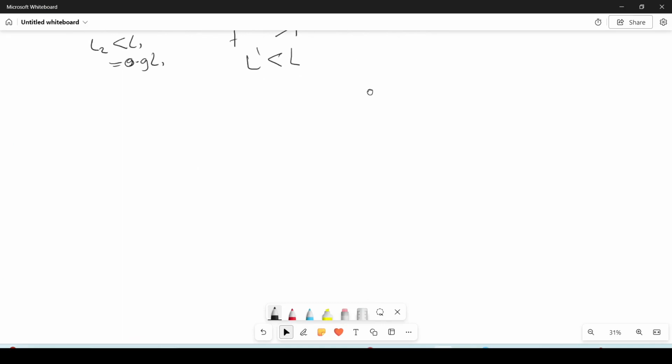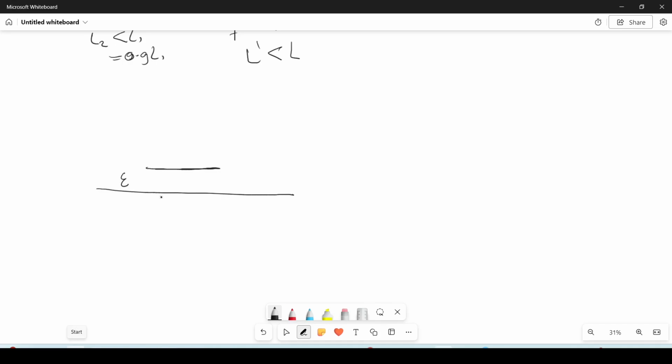When we have the patch antenna, one way of looking at it, for example, if this is the patch, this is the ground, this is epsilon, right? And this is epsilon like this, right? So one way of analyzing the patch, or any radiating element over the PEC, is to use the image, right? So this is the substrate, and this is the current, something like J or M, right? So I have the patch existing on a fictitious surface like this.